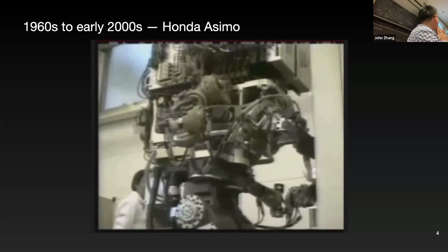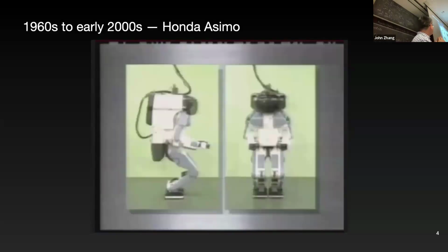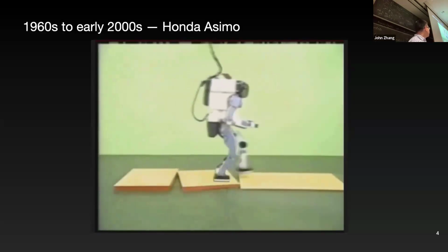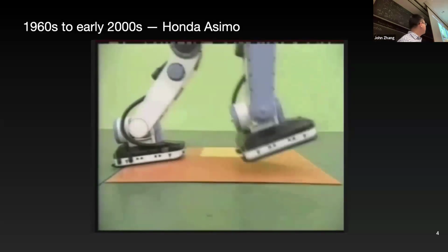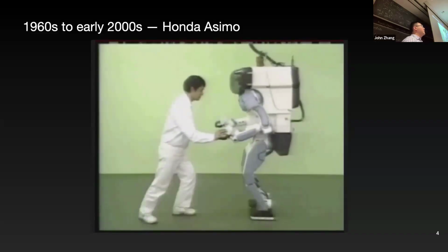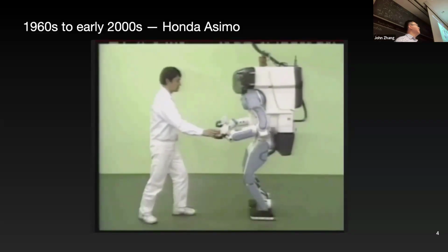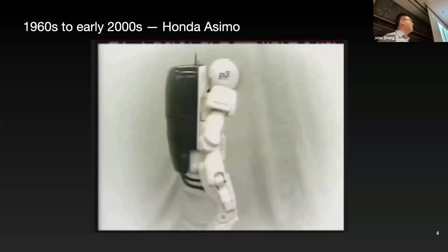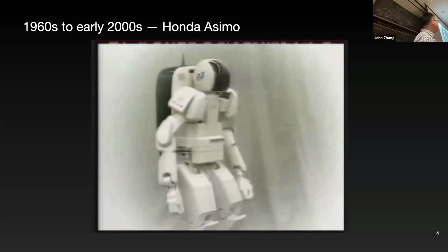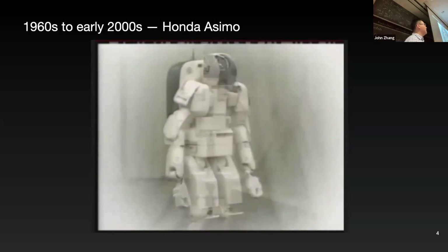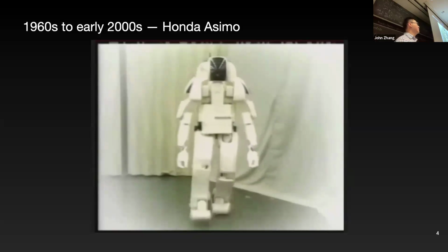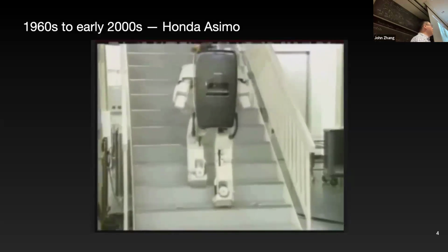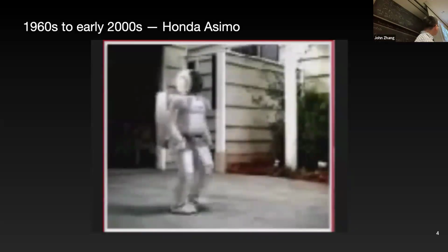You can keep watching this video. What they're doing is essentially treating the robot dynamics as a manipulator. And you can see the walking behavior is extremely slow, and the robot walks very carefully. With these assumptions, you're assuming quasi-static motions and you can't really do anything dynamic. In particular, unless you're using some special heuristics, your robot cannot jump in the air with two feet off the ground, because that would break the assumption that you're fully actuated and your foot is pinned to the ground at any given point.